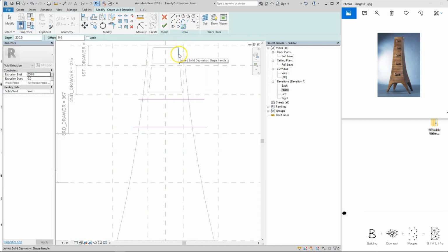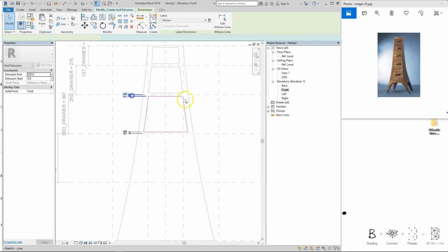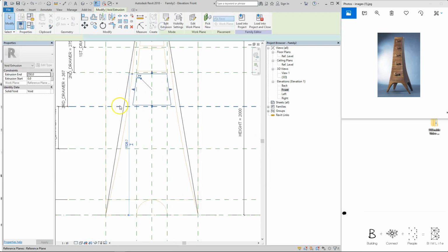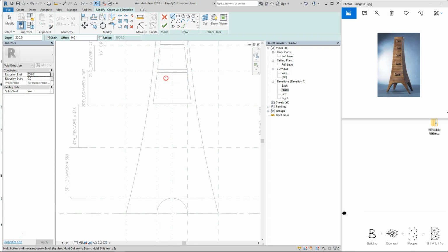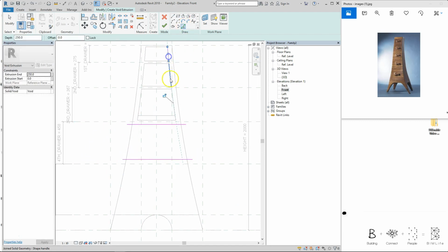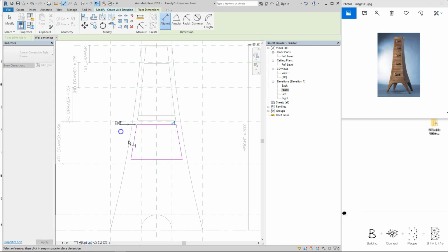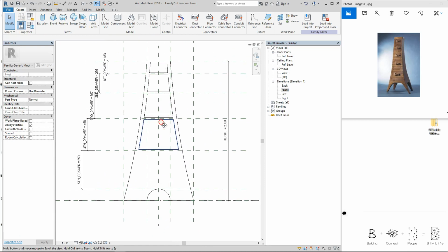use the pick lines command, pick the first drawer's curvature, remember to lock it, use the trim command, do a dimension, offset it as 15, lock the 15, press the green tick, do it again, oops, wrong one, create void forms for extrusion, draw two lines, use the pick lines command, pick, lock, trim, dimensions, lock it as 15, green tick, and one more, the last one, kind of tedious process.